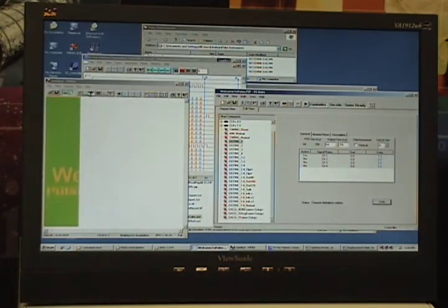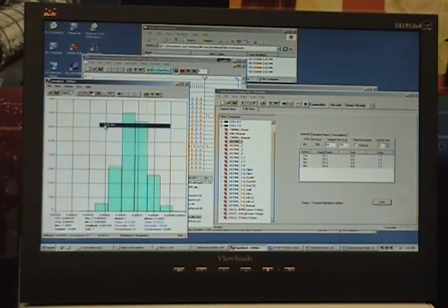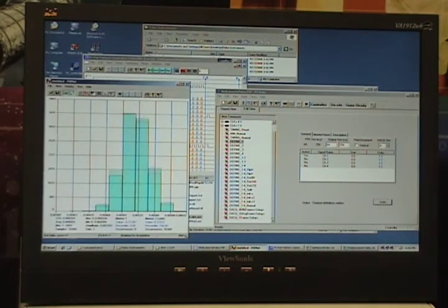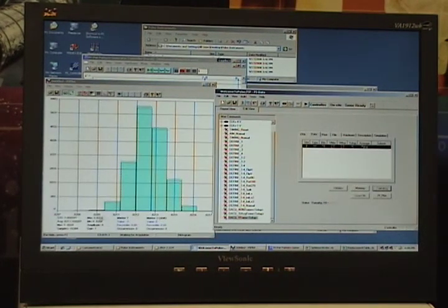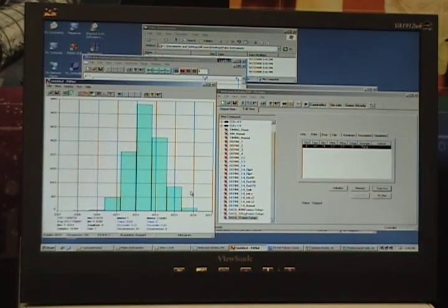Now let's look at noise performance. I'm going to use the timing from my test pattern, but instead of digitizing my pattern, I'm just going to short the input with a 50 ohm terminator. As you can see in the histogram view, the 1 sigma noise is just about 1 LSB. When we look at it in the grayscale view, with the contrast maximized, the noise looks random, with no visible periodic component.